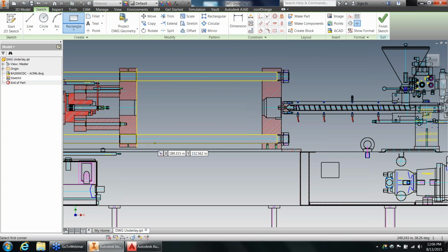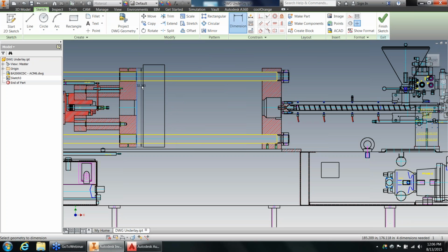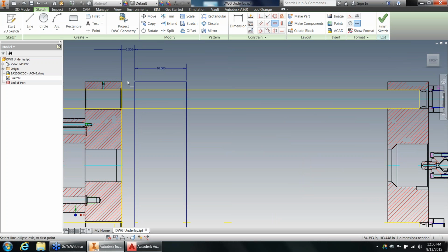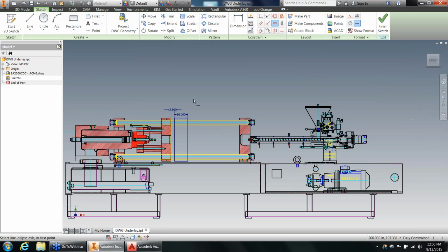then start using my drawing tools, apply dimensions to those pieces of geometry, and then use my other relationship tools to lock them together. Now, the important thing to note here more than anything else is that in the old methodology, once I imported this information into a design, this information was essentially hard-coded into the Inventor file, and it had lost its association back to the live DWG data.